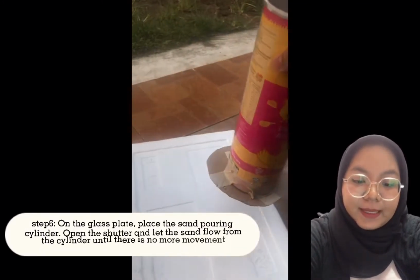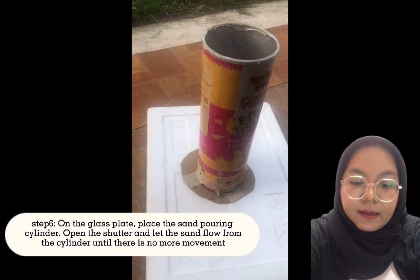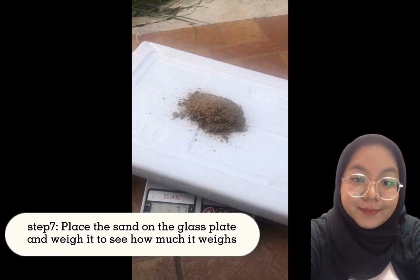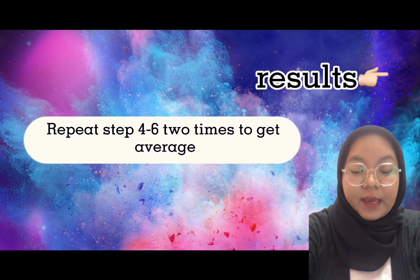On the glass plate, place the sand pouring cylinder and open the shutter and let the sand flow from the cylinder until there is no movement. And lastly, weigh the mass. Repeat steps 4 to 6 to get the average.